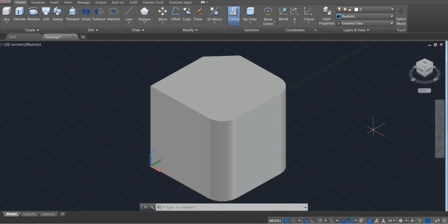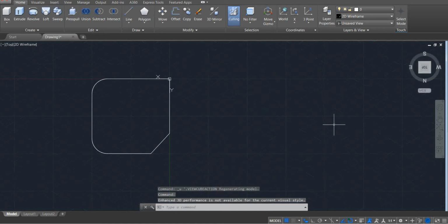So this is the key idea of the extrusion command: it converts any closed-loop two-dimensional sketch, and this sketch should be joined. If it is not joined, you're gonna end up with surfaces. You have to join the lines first, then you extend them in one direction by a specific amount to end up with a 3D solid. This is the basic idea of the extrusion command. Make sense?